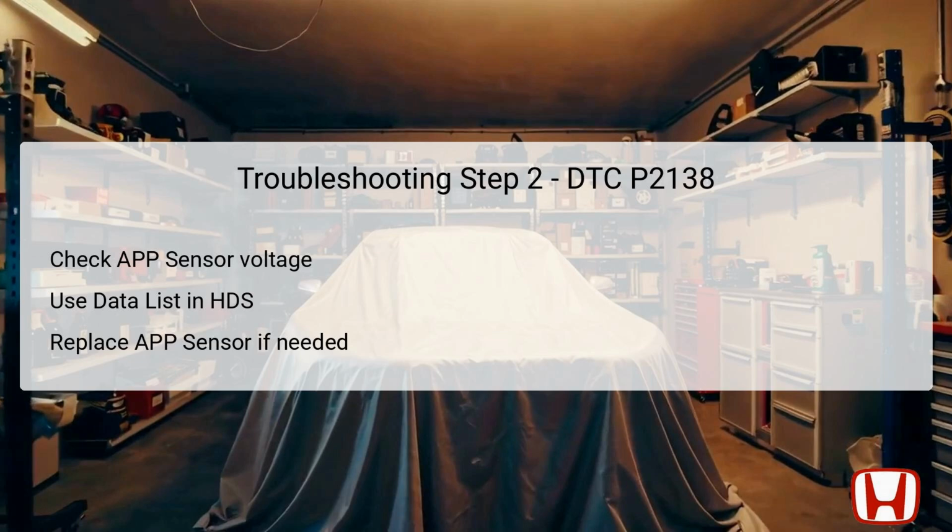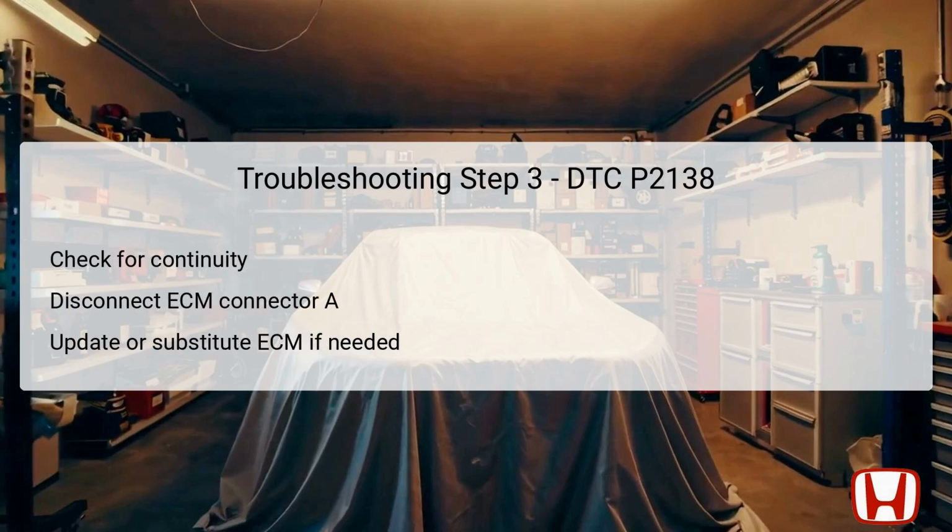Replacing the malfunctioning APP sensor is the recommended course of action, and following the replacement, it is essential to perform repair verification to ensure that the issue is resolved. This step is systematic and vital in pinpointing whether the APP sensors require replacement, significantly easing the repair process.